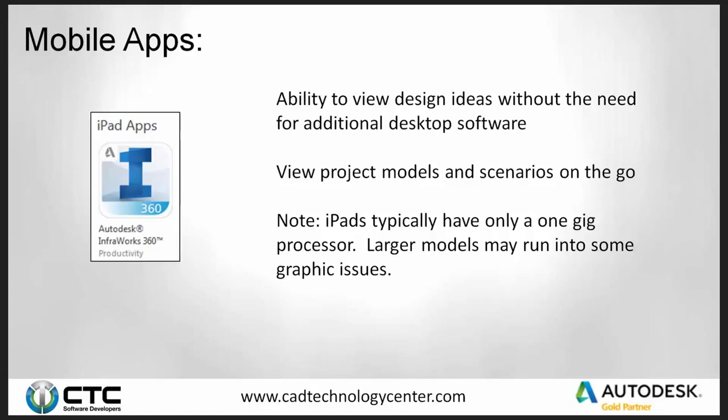iPads only being 1 gig, well, most of your models are going to be typically 800 megs to possibly 2 gigs, depending on your size. So if you run a model that is larger than a gig in file size, it might have a little bit of graphic issues. I've seen one where they had 50 wind turbines out there, but you only saw 20 of them because graphically it just couldn't show everything. So just keep in mind the size of your model, and is it bigger than 1 gig? Because if so, your iPad may run into a few issues.